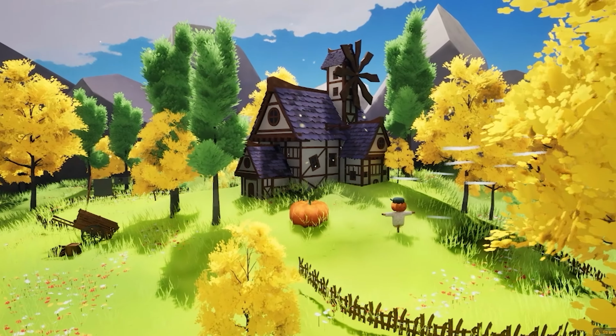The grass felt too dense, so I implemented another density filter node to thin out the ground and help with overall optimization. Generating the trees was pretty much the same process as the grass, but this time with more refining so that our trees don't fully cover our environment. We grab the spatial noise node to add our points back on and use a density filter to thin these points down into smaller sections.